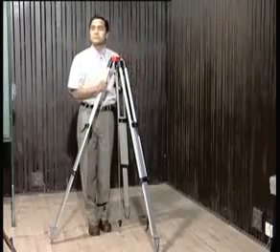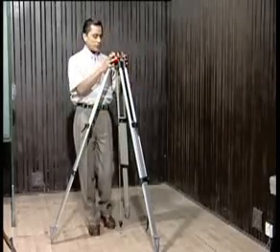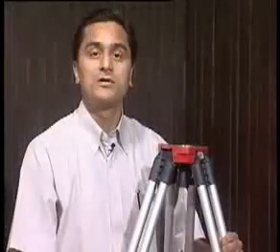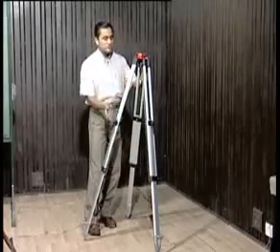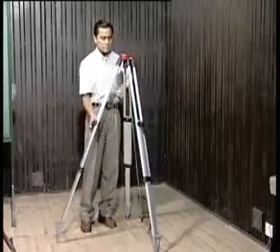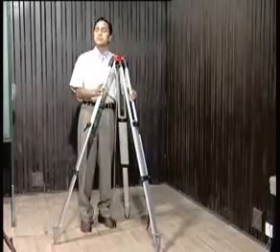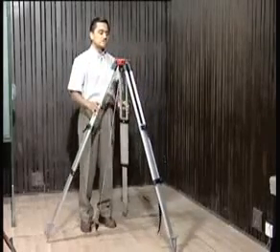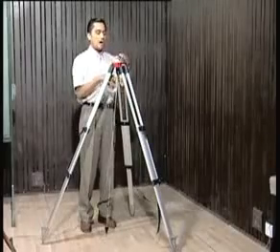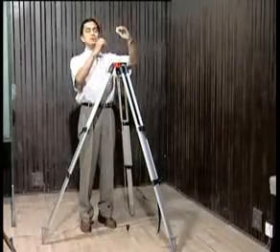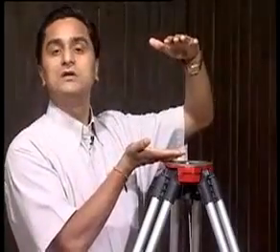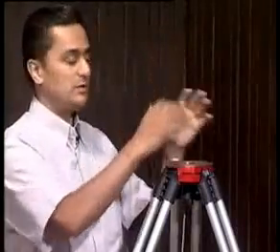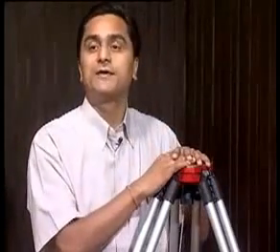So, well, I occupy this point. Now, when you occupy this point, you start with a tripod. A tripod, as you can see here, in this case, we can change the length of the legs. We all have the arrangements, and by this you can change the length of the legs. The idea is, we want to keep the length of the legs or the height of the tripod in such a way that after keeping the theodolite on this, the eyepiece should be at my eye level. So we know approximately the height of my theodolite and that's where the eyepiece will be. So this is how I decide about this particular height.